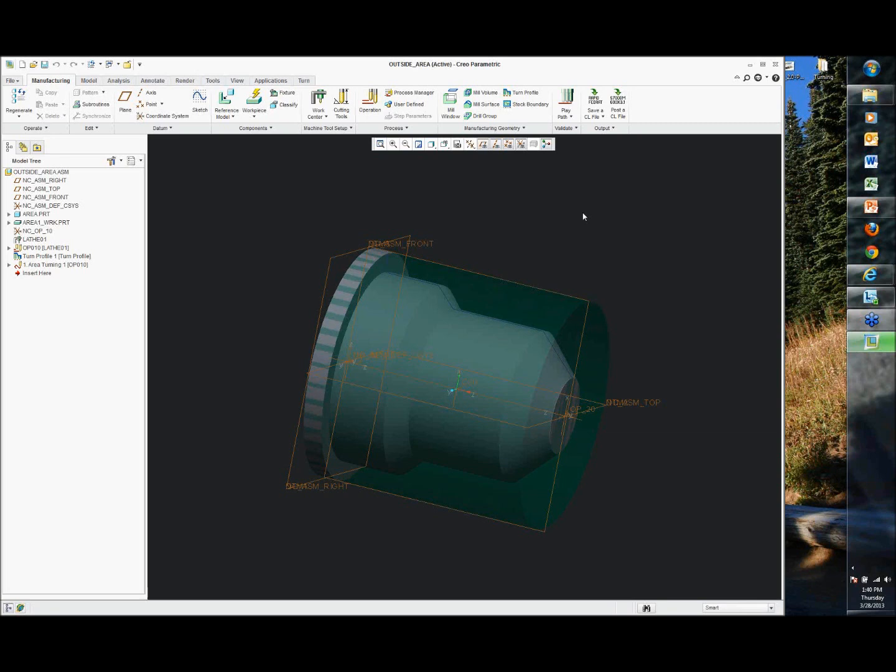I know what you're trying to accomplish there, but I don't know that. The material removal doesn't always work correctly. So you run something through on an NC sequence, you export it out or save it off in a CL file, run it through Vericut, and then when you do the post, it doesn't actually come out the right way.